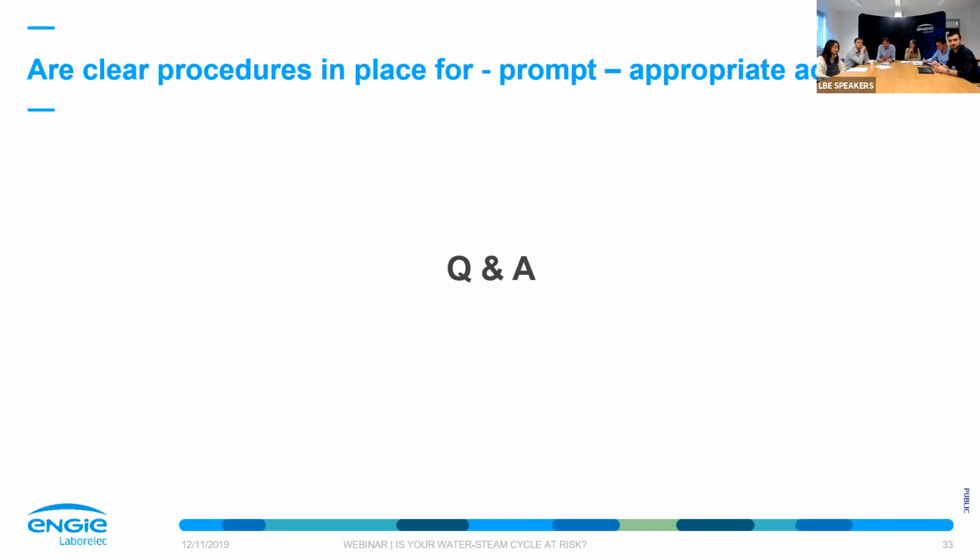I've seen it a few times in power plants, and it seems that reliability is not higher than for sodium analyzers. But anyway, we stay very interested to have your feedback. For the moment, we don't have the information that chloride is more reliable than sodium. So there's a good compromise, economically speaking, that sodium is the preferred alternative for the moment.